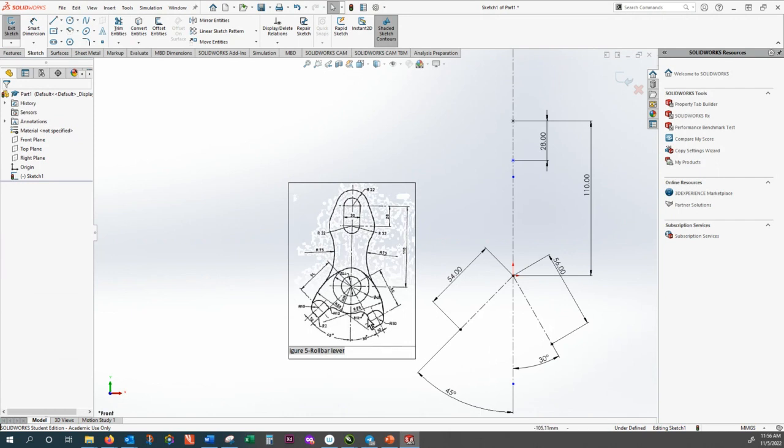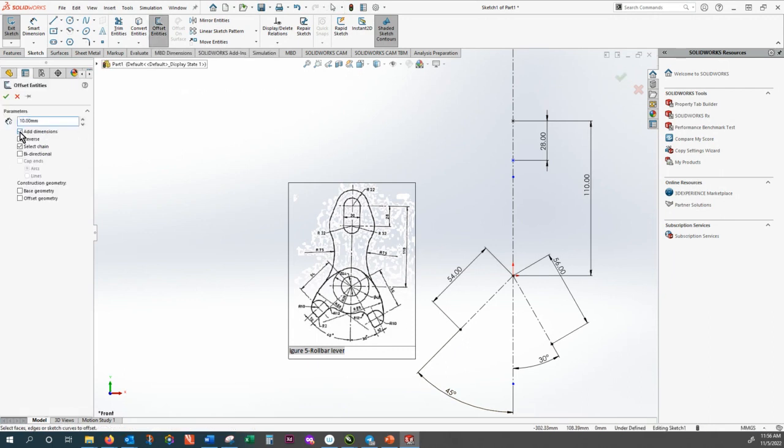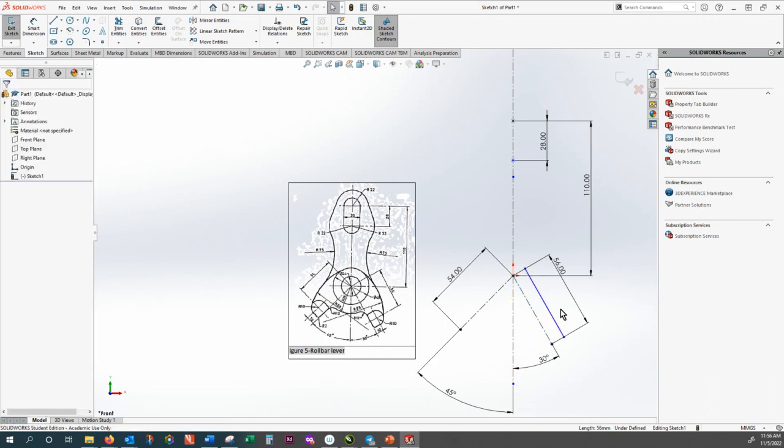Now I managed to get this line, not that line. So how do I make the second line and this one? There is a command here called offset. Offset does a parallel transformation. So I do an offset, just get rid of the existing options. The distance between this line and that line is 10, so that 10 is here. I select that line, but the default offset is toward the down. I want this side, so I click that side.